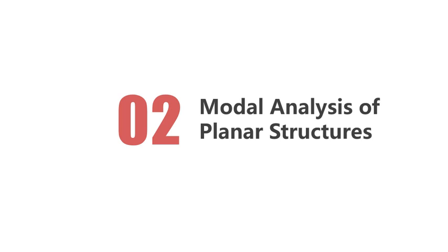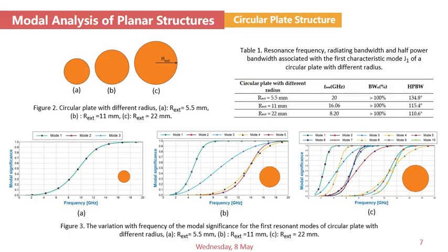Now we move to explain the work proposed in this paper. Firstly, we have a modal analysis of planar structures. The first study consists of circular plates with different radii. These plates were analyzed using the theory of characteristic modes to compare the resonant behavior.